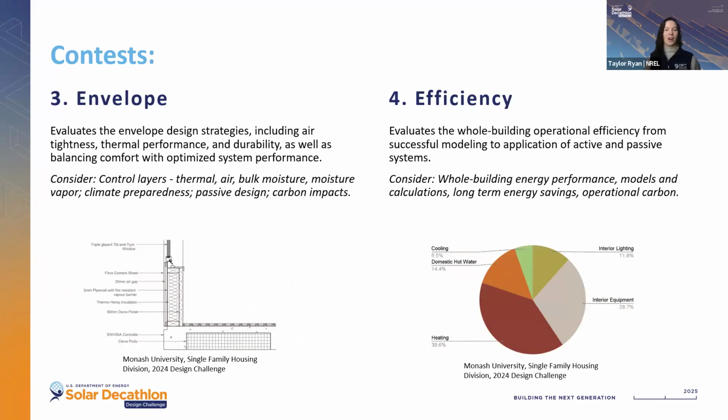The third contest is envelope. This contest evaluates the envelope design strategies, including airtightness, thermal performance, and durability for how well the team balanced comfort with optimized system performance. Through this contest, students will be asked questions like how effectively they used passive design strategies to reduce active system capacity requirements.